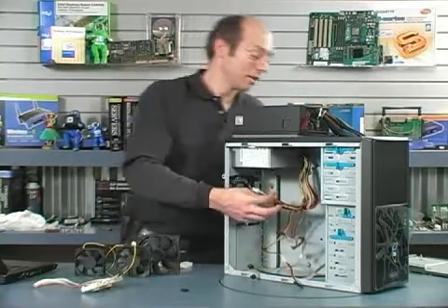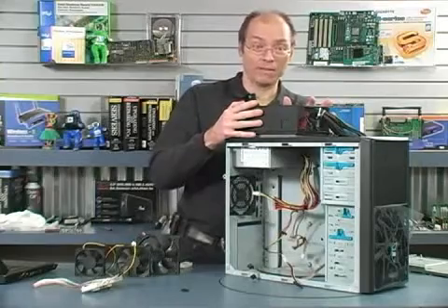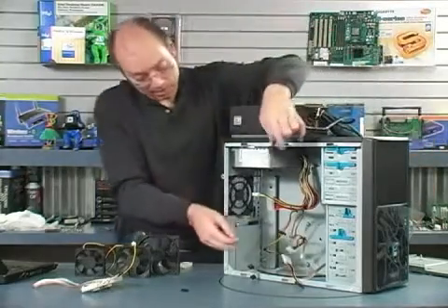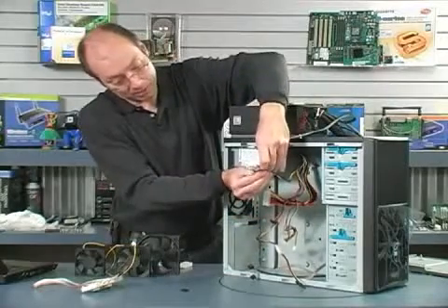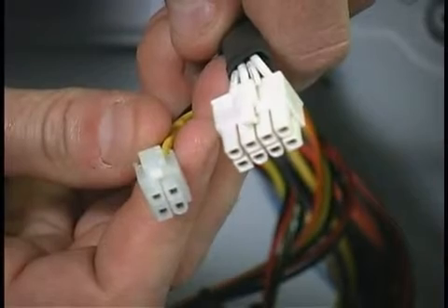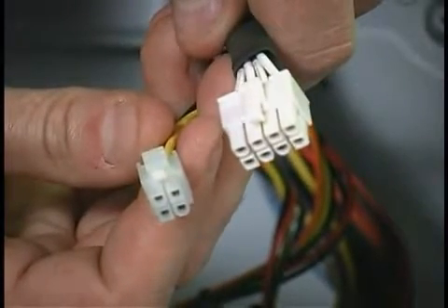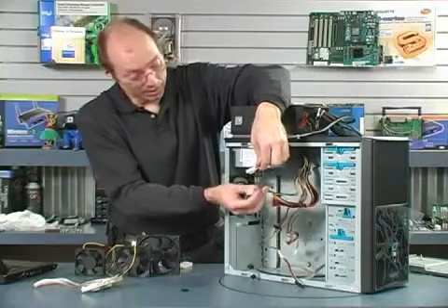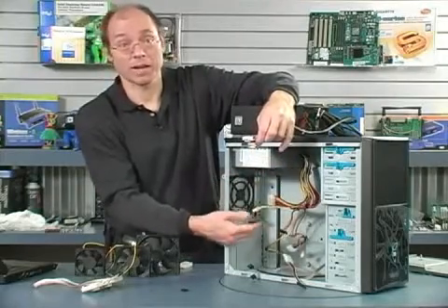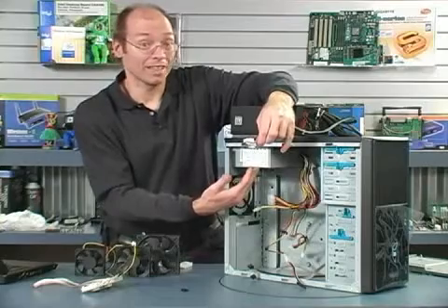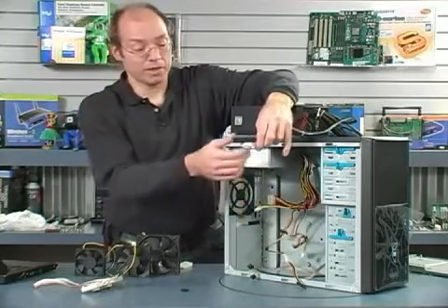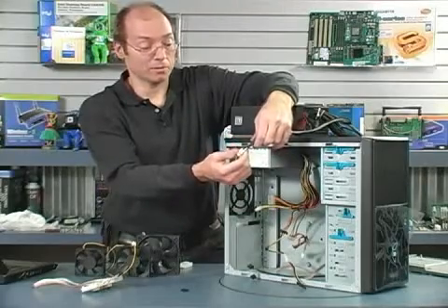So what you'll want is to find a power supply like this one. This is a bigger, heavier duty power supply I have on top here. And this one has an 8-pin motherboard CPU power connector. You can see the difference here, 8 pins versus 4. Now you can get adapters to turn the 4-pin into the 8-pin, but that doesn't provide more power. So the idea is that if you need a bunch of adapters to make your power supply work with what you have, you probably don't have an adequate power supply to begin with. While an adapter here and there is okay, if you start using adapters for everything, it just means you don't have an adequate power supply.